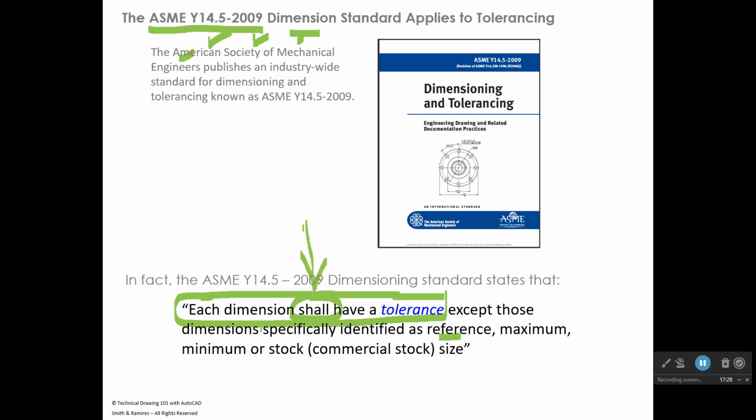Well, if you had made a drawing that had tolerances on it and you gave it to the manufacturer, they need to make the parts within those tolerances. If they do that, then you owe the money for that part. If they're outside the tolerance, you wouldn't owe the money. That's what you would put into your contract with the manufacturer. So this becomes contract language between organizations. So it's really important. And so tolerances are a really good thing.